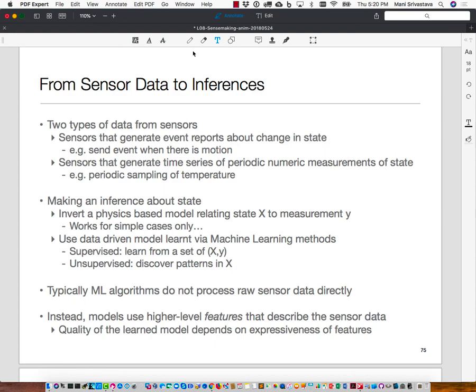So the right set of features is important. Another thing is that you don't want duplicative features. Think of features as themselves being little sensors. Each one of them is telling me something about the data. If I have a biased set of features, that is, most of the features are telling about one property of the signal, then I'm getting duplicative information, right? So you want sufficiently representative features also. Selecting features is extremely important anytime you are processing and trying to make that inference out of them.